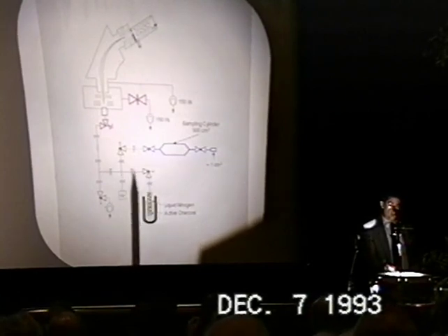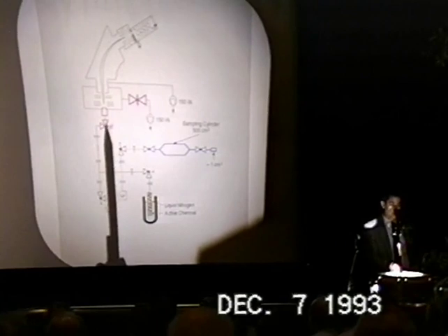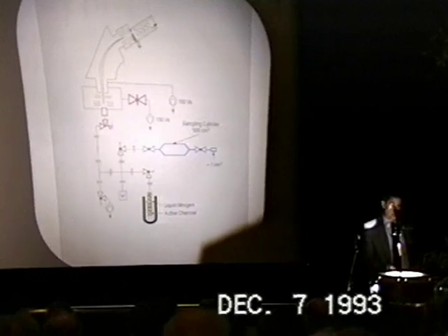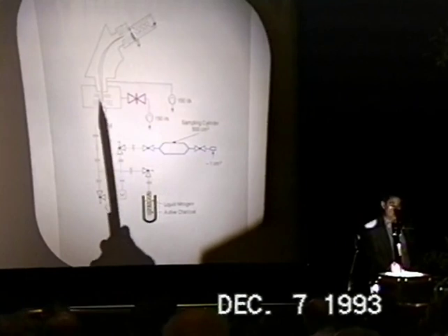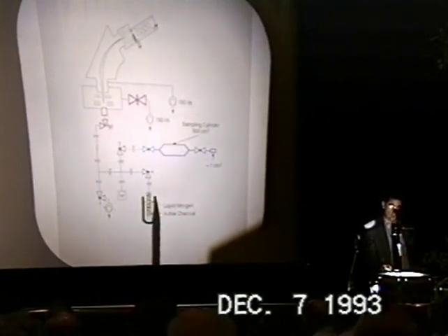What we are looking for is to lower as much as possible the partial pressure of nitrogen before getting our sample into the ion source, in order to be able to open the dosing valve as much as possible without deteriorating too much the pressure inside the ion source, and so the resolution and the sensitivity itself.